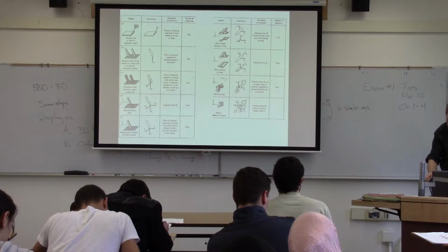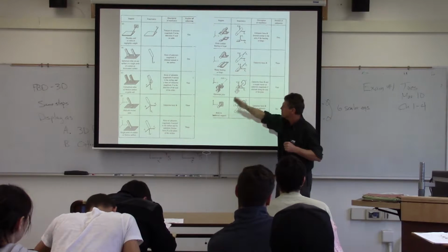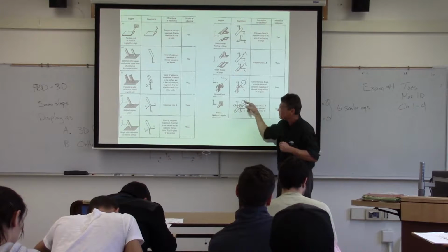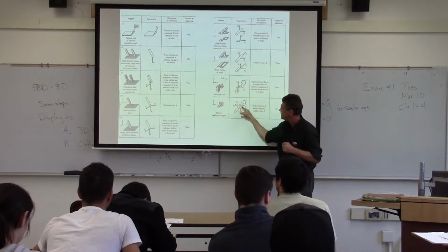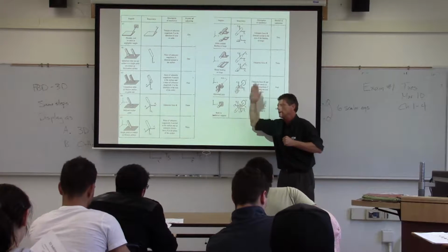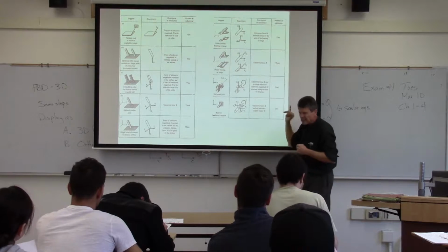And then there's finally the built-in case there where it's basically stuck into the wall, trying to get it to go any direction there. You're going to have the 3 forces there substituting. But any sort of rotation, it's not going to be able to twist this way, go up and down this way, or be able to go this way. So that'll use up basically all of our equations.